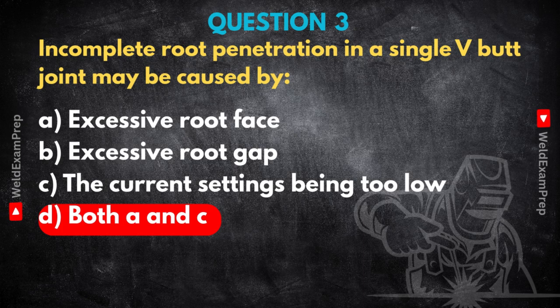That's a really good question because visually it can be tricky, and sometimes they do occur together. But there are telltale signs. For incomplete root penetration, the most obvious sign, especially on a single-sided weld, might be the complete absence of a root bead on the backside. Okay, nothing came through. Or maybe a very narrow, inconsistent, sucky-looking bead. It's fundamentally about the lack of material making it through. Sometimes you might see concavity at the root from the front.